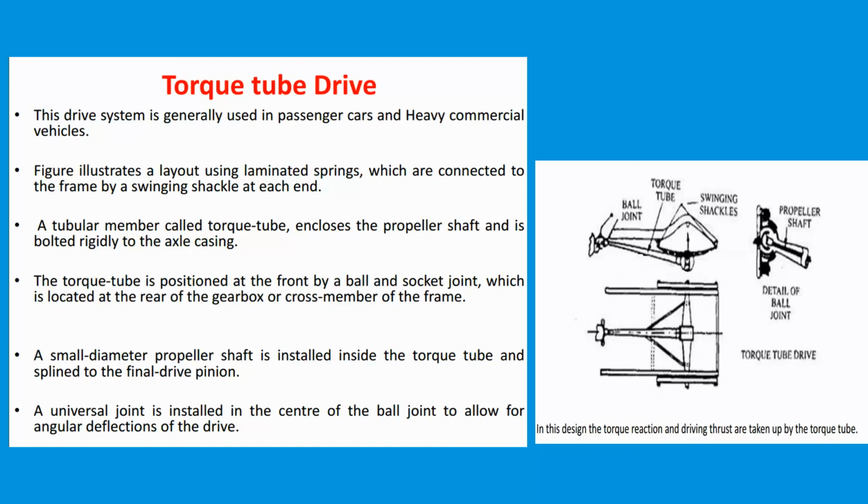The torque tube design is typically heavier and securely ties the rear end together, thus providing a rigid rear end and assuring good alignment under all conditions. However, because of the greater sprung weight of the torque tube and radius rods, there may be a little hopping around of the rear end when cornering fast and on washboard roads.